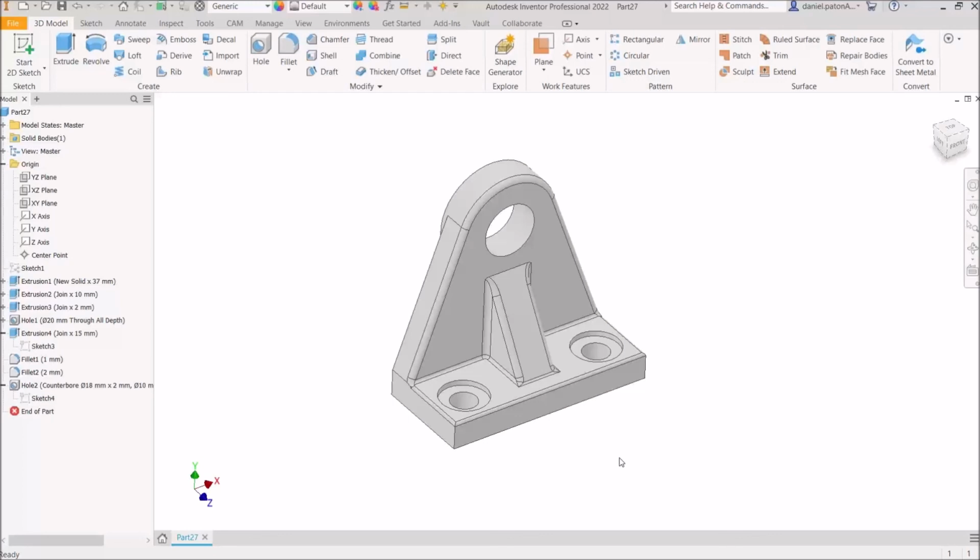In this case, we used extrude, just to extrude some geometry. And then we can always go back and add additional sketches in or create additional extrusions, or we can go and edit those sizes if we need to manipulate this object. Okay, and those are the basics of how we create our first part.